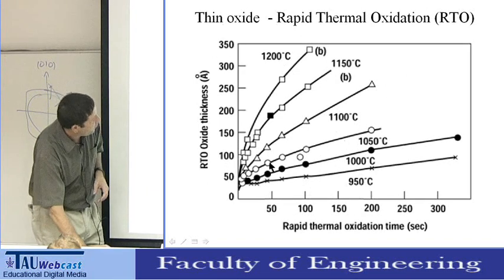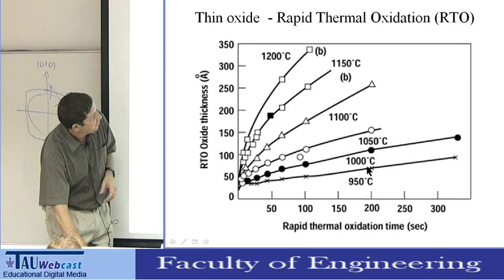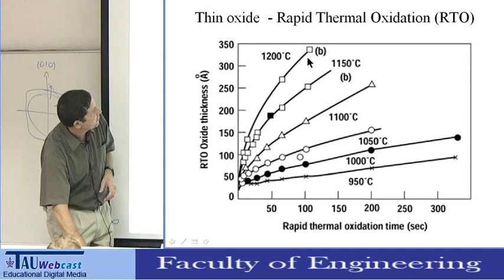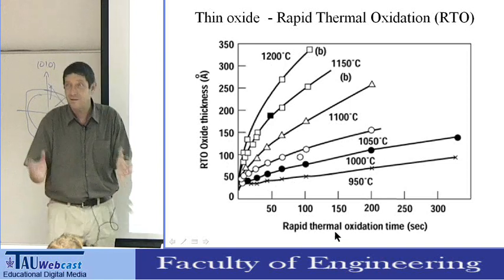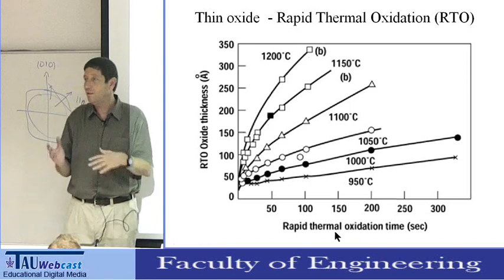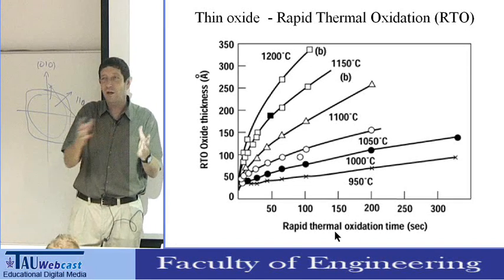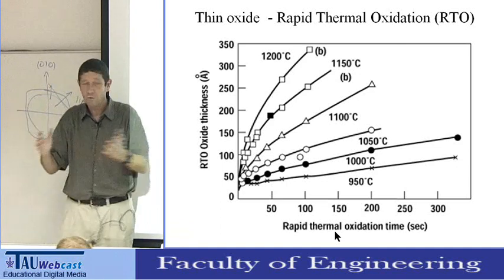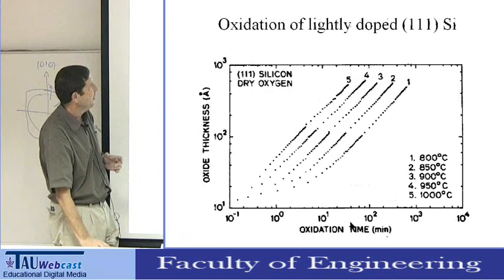If you notice, the oxidation versus time is kind of parabolic, it can be linear or going like the square root of time, which fits nicely the Deal-Grove model. The Deal-Grove model describes this function, which can be linear or parabolic, or a square root of time. So it fits nicely the data.